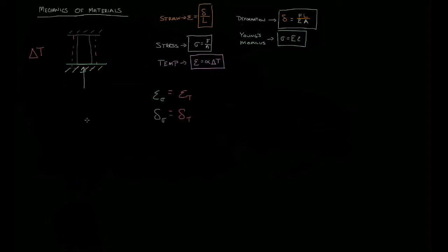These types of problems, where there's an internal stress or an internal strain that happens because of the geometry or the temperature, show up a fair bit. These are problems that can't be determined by use of simple statics. Hence, we call them indeterminate problems. And today, I'd like to think about how to approach these problems.